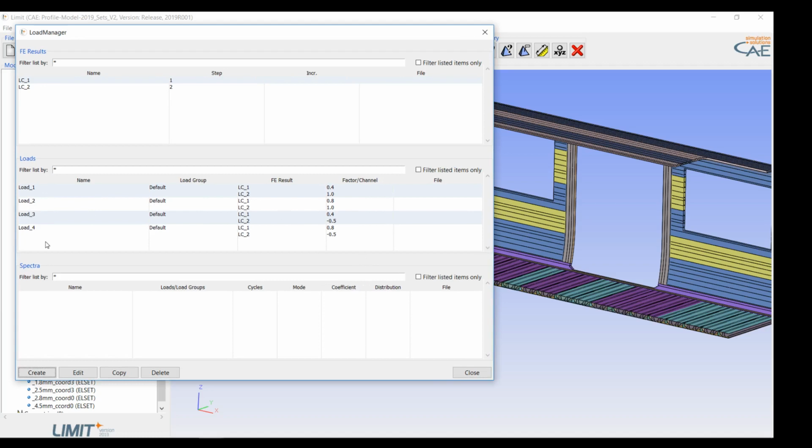When LIMIT runs the assessment, we have 2 searching methods. The first one is simply running through all the loads in a linear way and looking at each load case only once, storing maximum and minimum contributions for each stress component relevant for the weld. The other possibility is to generate all possible load case pairs and do an independent endurance limit analysis for each possible load case pair.